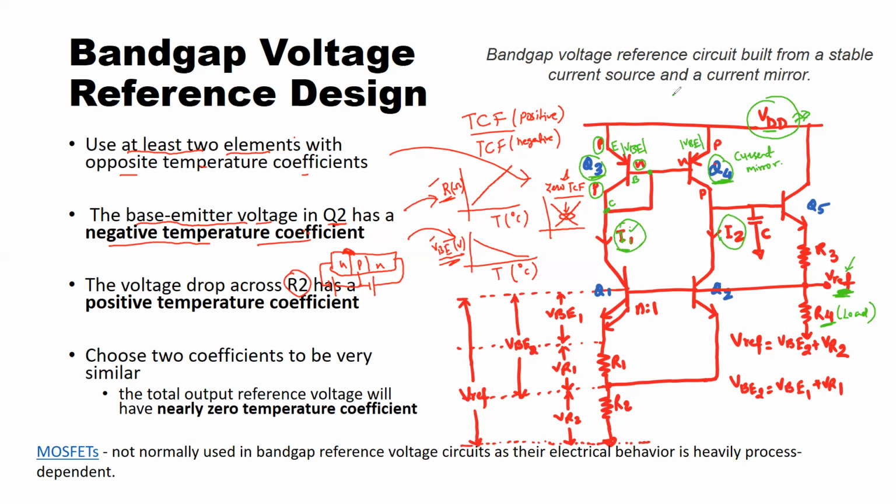So my I2, which is an output current, will be equal to I1, which is an input current. Once that is done, I'm using the bottom two transistors Q1 and Q2 to sink those currents supplied by Q3 and Q4. So I1 is coming to Q1, I2 is coming to Q2.